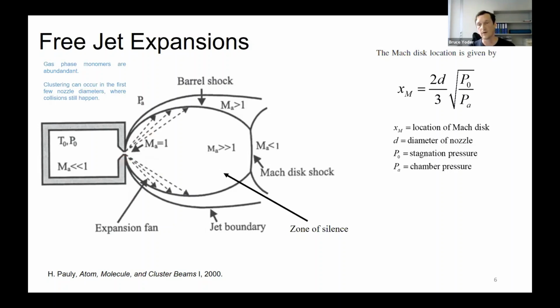starting from the rim of the nozzle with so-called Prandtl-Meyer expansion waves, indicated here with these dashed lines. The flow becomes supersonic, with the Mach number becoming much greater than 1, and the Mach number increases with increasing distance from the nozzle. Since the supersonic flow is unable to sense the boundary conditions downstream, it overexpands to pressures lower than Pa.